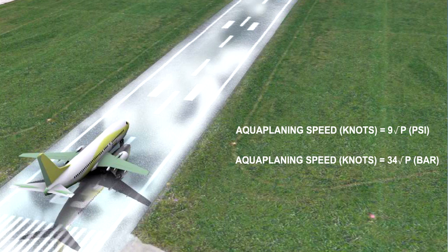The possibility of aquaplaning increases as the depth of the tread is reduced. It is therefore important that the amount of tread remaining is accurately assessed. The coefficient of dynamic friction between the tyre and the ground will reduce to very low values, typically 0 when aquaplaning. Neither nose wheel steering nor braking will be effective when the wheels are aquaplaning.